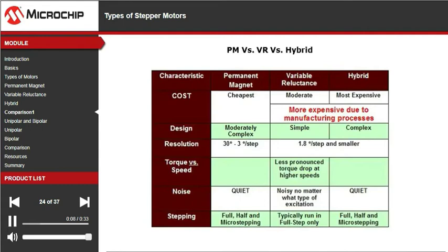The first consideration is cost. The permanent magnet motor is cheaper due to the manufacturing process. Hybrid and variable reluctance motors have a more intricate fabrication process due to their geared rotors. The rotor is actually made up of thin laminates of soft iron, which reduces the occurrence of eddy currents within the rotor. A similar process is used when fabricating transformers for power supplies.